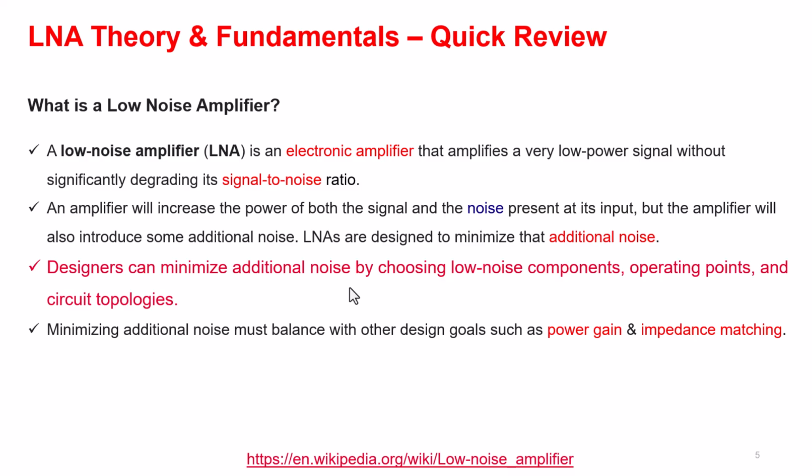Now most of you already understand what is a low noise amplifier, and it's a pretty important piece, especially in the receiver subsystems. Now this special category of amplifier is designed such that it boosts your signal to noise ratio at the output. What it means is the signal gets amplified, but noise gets amplified by a very small amount, and that is called noise figure of low noise amplifier.